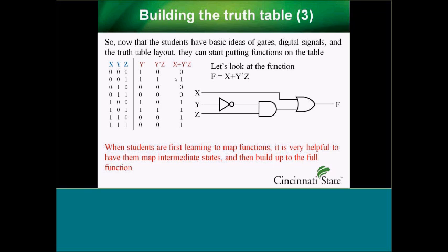And so what I tell them is, okay, you've got a complicated circuit. It doesn't work. That means somewhere in this circuit it fell apart. So you need to go back and you need to check. You need to check here. You need to check here. You've got to figure out exactly where it fell apart. And what do you expect? And sometimes you have to go through the entire truth table for each one of those. You look at all the signals for each one of those things.